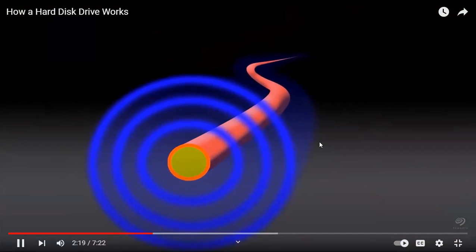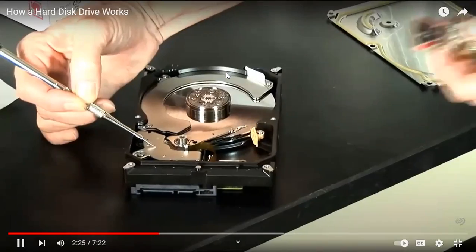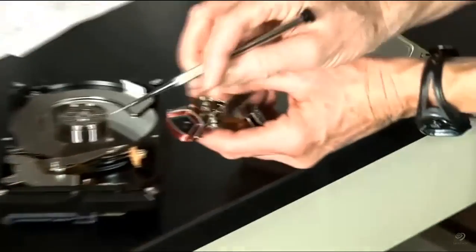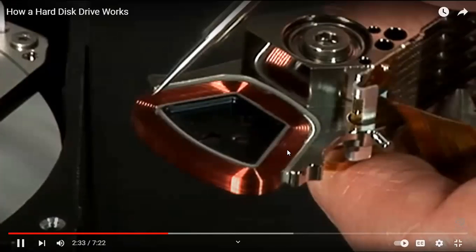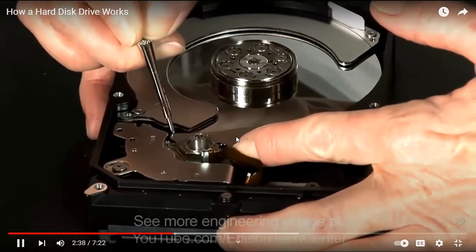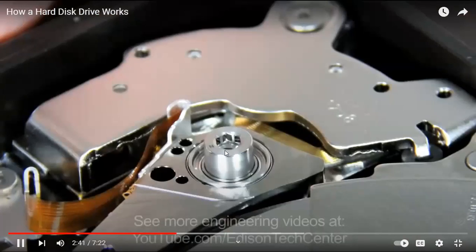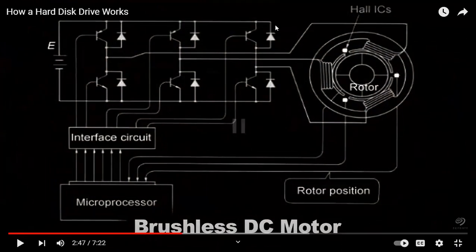So how we are using that here is that there is a coil, which is actually hidden under this magnet. Under this plate, there's a magnet, and below the magnet is a coil. The driving force is the coil current, right? By using the magnetic forces on that coil, we can move the actuator arm with the help of physics, right? So we can use the electrical charge to move the back end of the coil in one direction or the other. Right here we see the motor that spins the media. So that is how they design this kind of hard disk, right?